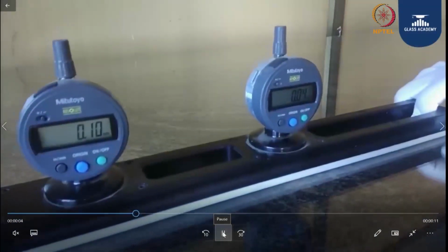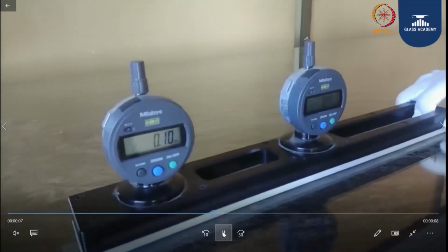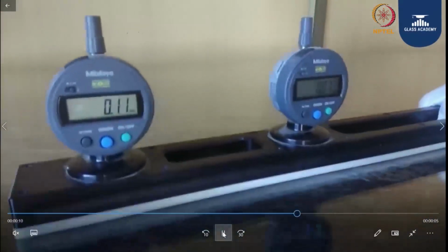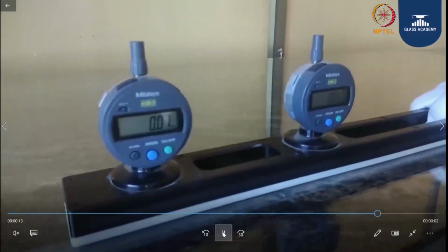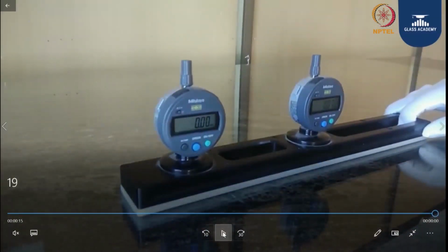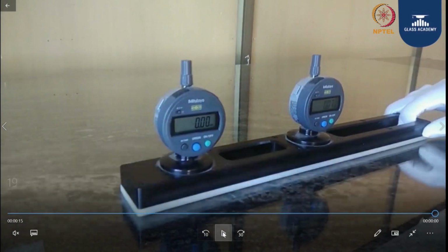You can find here the roller wave gauge which has two dial gauges. If you see the center gauge, right now it is showing 0.06, 0.05. You need to focus on the center gauge. It is showing 0.06 again. And if you see, on an average it is fluctuating between 0.04 to 0.07. So the roller wave is nothing but the glass is moving on rollers and it is going through peaks and valleys. So we need to calculate the summation of the peak and valley. If you see the minimum value in this, initially it came 0.0 and the maximum value it is showing is 0.07. So the roller wave is nothing but the summation of the peak and the valley.